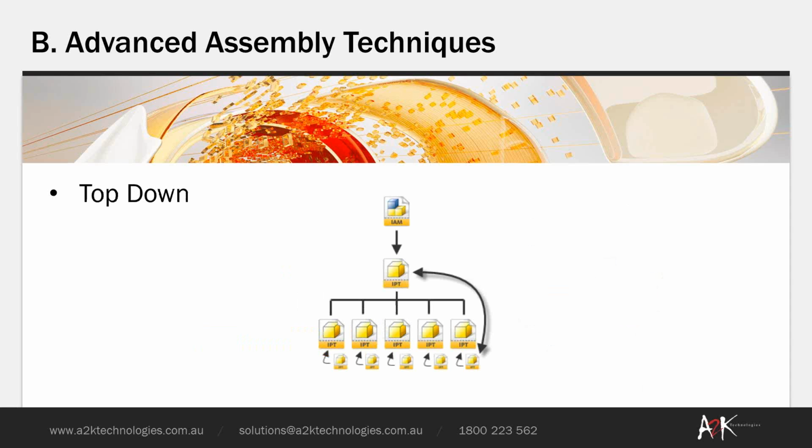So that brings us to a third approach, which is top-down design. In this top-down design scenario, what we do is we start with a part file. We basically design our entire assembly within that part file, or reference to a part file. And from that single part file, we then create an assembly. Okay? It'll seem clear once we get into Inventor and get started on it.